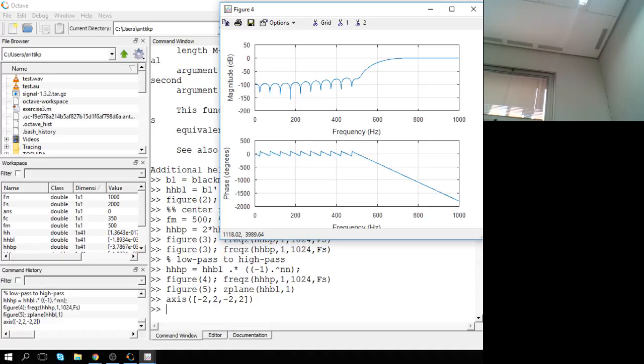And then the implementation of that system is such that you simply have a system which calculates the new impulse response by taking B times the low pass impulse response plus M times the band pass response plus H times the high pass impulse response, and use this impulse response in a system.